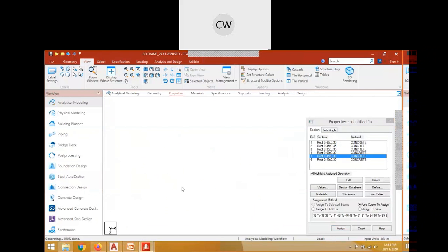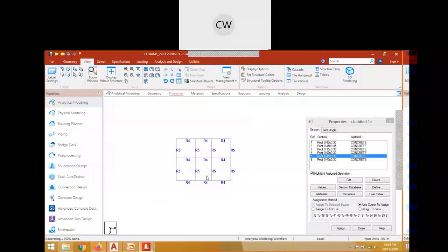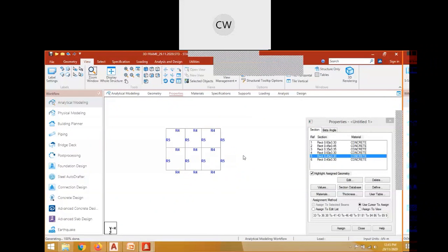Now you can go to plan and then you can safely model wherever you want. So I just wanted to show you this command, how to work on a particular level. So this is the top level now. Here I will model this particular beam at this level, and then we will replicate that beam to other levels. Okay, fine. So let's do this.